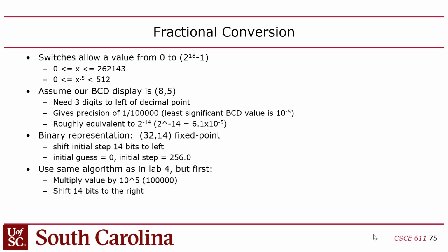Anyway, Lab 5 is where we're going to try to do a superscalar, extend the CPU to execute 2 instructions per clock, right? So we're going to add another ALU, we're going to add more ports to the register file, and we're going to add another control unit so we can double up, right? Which is principally how you get more performance out of CPUs: you get more instruction level parallelism, you execute more instructions in parallel, right? But that requires some additional things in the assembler too that we have to modify. Okay, but I'll talk to you guys individually about that.